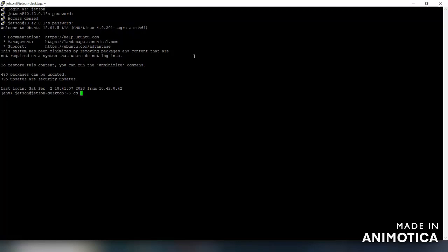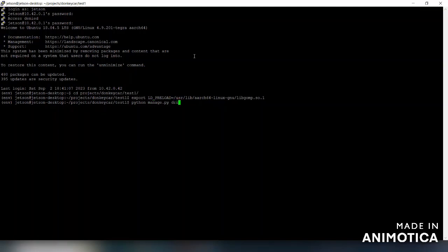Once I've transferred the trained model to the physical donkeycar, I use PuTTY to connect to the physical donkeycar and navigate to the directory of the donkeycar application inside of the physical donkeycar. The command shown on the screen is executed to prevent a memory error from occurring when the trained model is loaded.